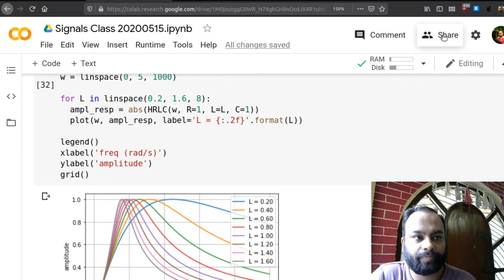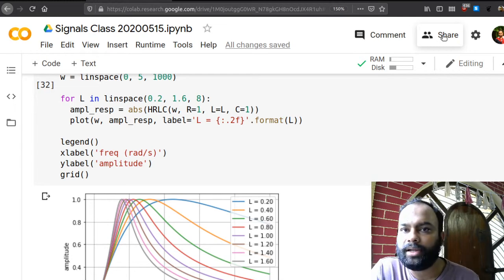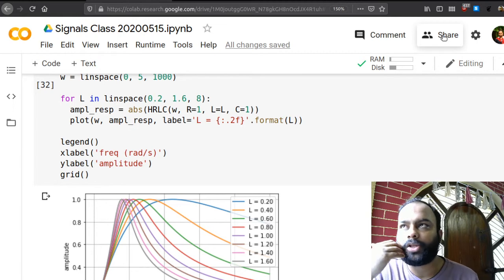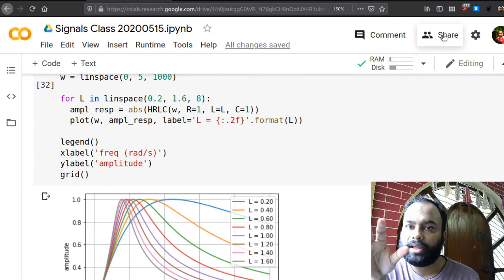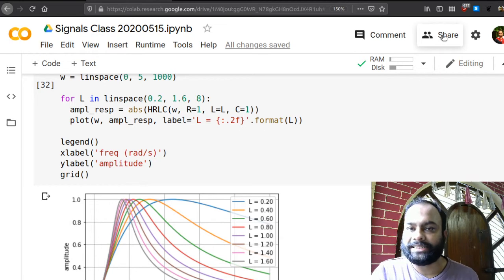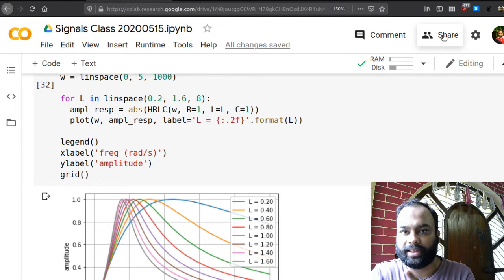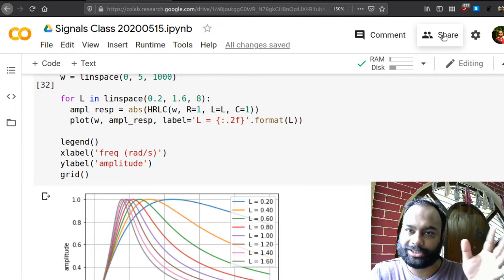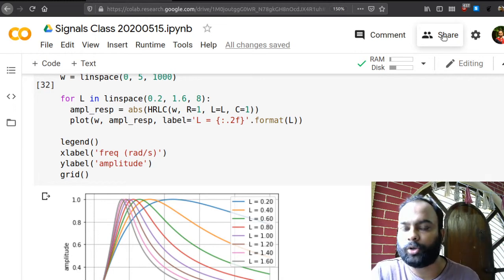Just to give you a hint, we have already talked about the sinusoidal steady states, right? If I want to analyze the transient states, then the Laplace transform becomes very important. So we have steady states, and whatever happens between 2 successive steady states, we have transient states, and the analysis of that will be the whole purpose of our control system engineering classes. And for that, we shall require Laplace transform.